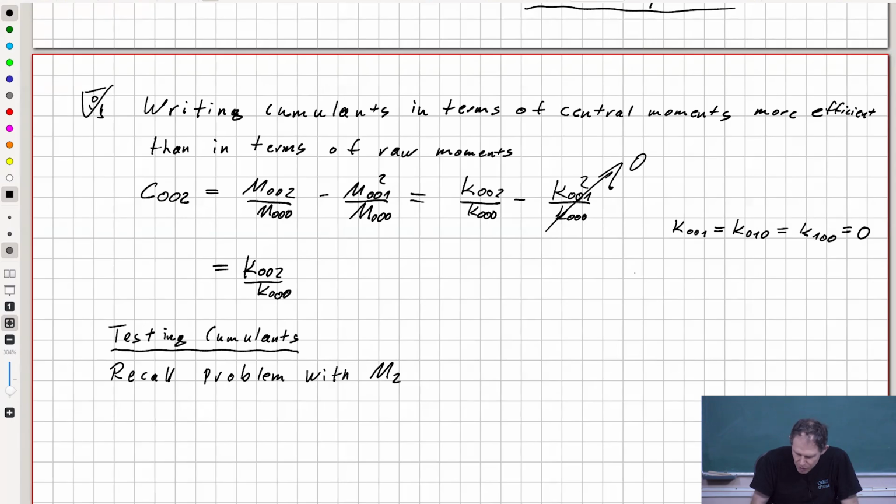With the M211 moment, you remember this is present in D3Q27. It's not present in D3Q19. This is why this method has been much more popular in the past, because it does not come with this problem.